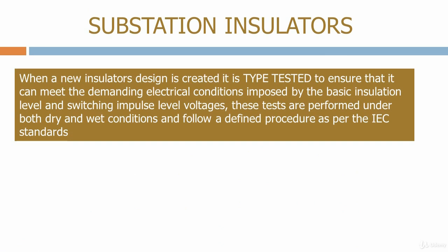When a new insulator design is created, it is type tested to ensure that it can meet the demanding electrical conditions imposed by the basic insulation level and switching impulse level voltages. These tests are performed under both dry and wet conditions and follow a defined procedure as per the IEC standards.